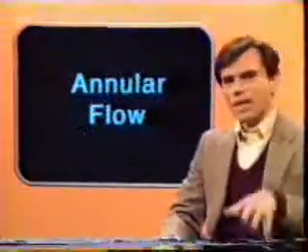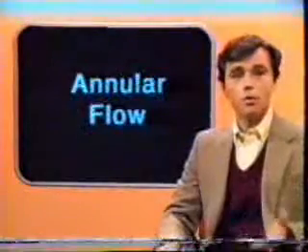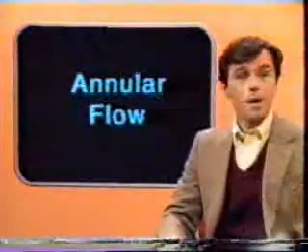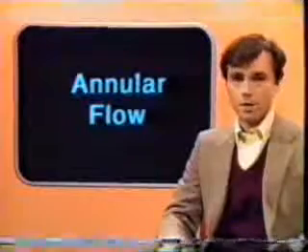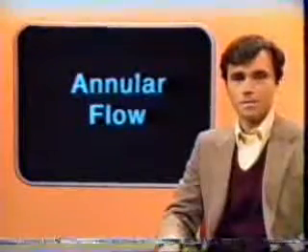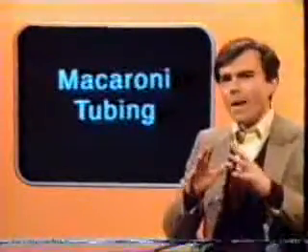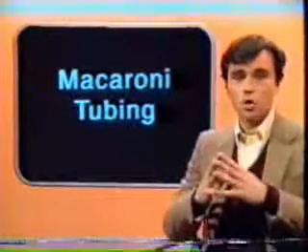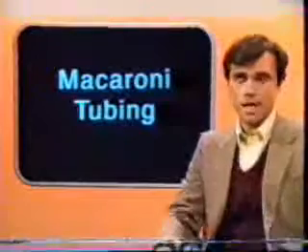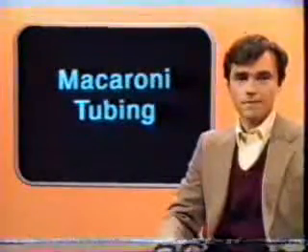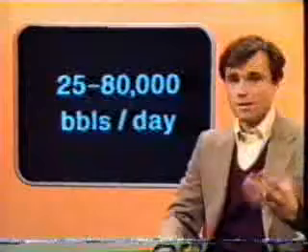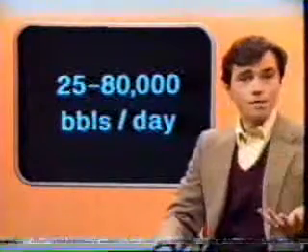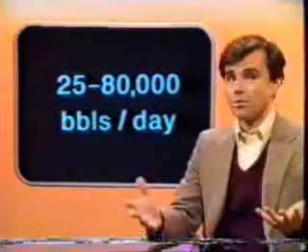If we choose instead to inject gas down the tubing and produce the fluid up the annulus, it is possible to lift up to 80,000 barrels per day using continuous gas lift. When small macaroni tubing strings are used, it is possible to obtain production rates as low as 25 barrels per day using continuous lift. The range of continuous gas lift, then, is anywhere from 25 to 80,000 barrels per day.